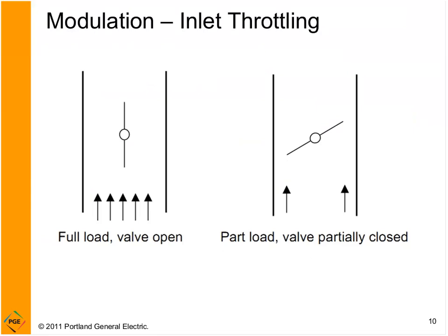Okay, so here on the left, we have air whooshing in to the inlet. Just as you can see in the arrows above, the air is going up through the inlet past this butterfly valve, just like an old-fashioned butterfly valve in your car in a throttle body or a carburetor. And then off it goes. Now this butterfly is fully open, so this allows the compressor to put out as much air as possible, or fully loaded.